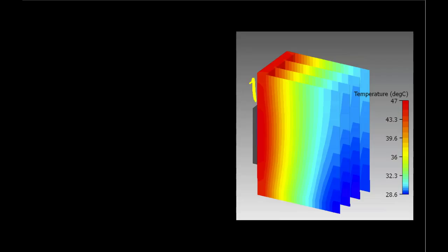On this edge, you've got a hot CPU or other component generating heat, and out here you have cooler temperatures. The distribution of heat within the heat sink obeys the heat equation. The heat equation, which is a partial differential equation, can be solved using frequency domain analysis. There is no intrinsic frequency associated with the heat, but the mathematical techniques of the frequency domain analysis make it possible to analytically solve these sorts of problems.